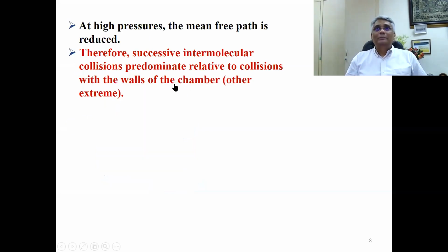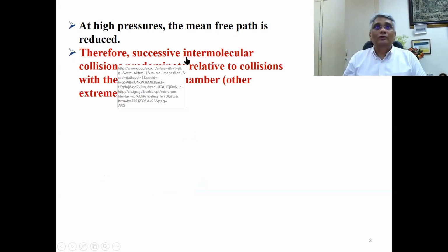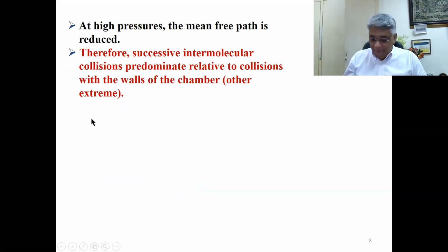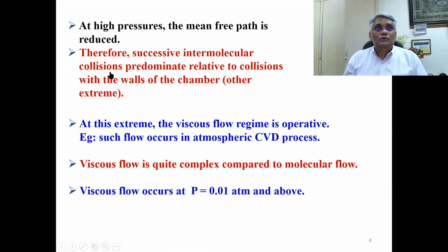Now at high pressure, the mean free path is reduced. Therefore, the intermolecular collisions predominate compared to collisions with the walls of the chamber. This is the other extreme. At this extreme, there is collision happening between the molecules, where at high pressures, low vacuum.